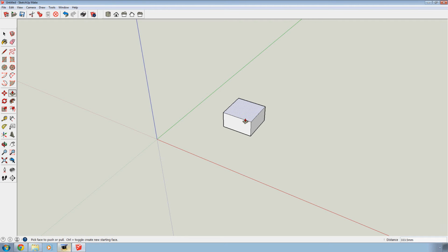Standard height for a kitchen worktop is pretty much 915, sometimes 910. But I need to allow for a 40mm worktop, so 915 minus 40 is 875. Virtually every kitchen unit worth the name has got adjustable feet now anyway, so I'm going to set this one up for 875. I'm not going to attempt to draw the feet in. So I'd punch in 875, press return, and there it is.